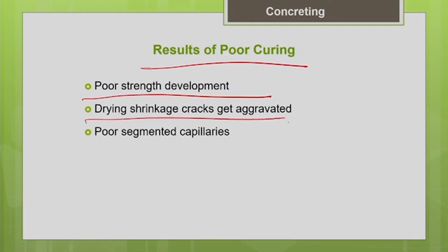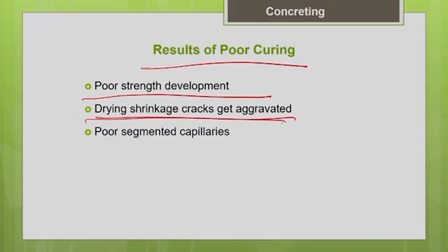Another important thing is that shrinkage cracks may occur, if the rate of evaporation of water from the concrete is very high. You know that concrete is weak in tension. So, drying results in a build up of tensile stresses in the concrete, which results in shrinkage crack development. So, to avoid shrinkage cracks also, we have to start the curing as early as possible.